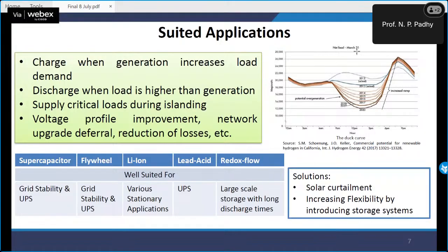So that is being catered. But for a particular duration of 7 to 8 hours, the synchronous machine will reduce its generation. It will take maximum from your PV and a little bit from the synchronous machine. Maybe 70 is the requirement, 50 from PV during 11 o'clock and 20 from the synchronous machine.